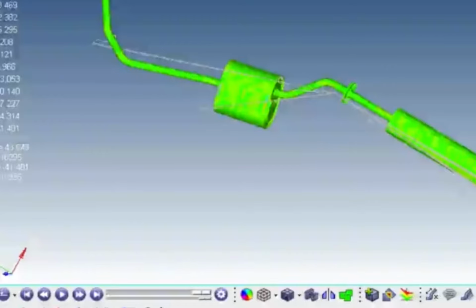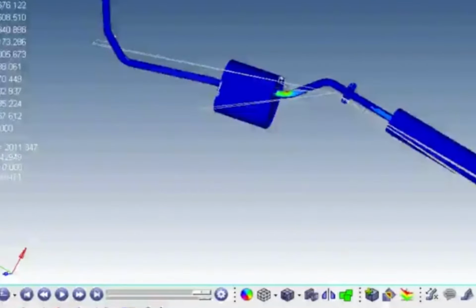So we're reading in the model file. We're reading in the element worst results, and in the results set, we have 20 different quantities. I'll go through and explain what each one is. So we have the various moments of response, starting off with the 0th moment, first moment, second moment, and fourth moment. Now these aren't quantities that you will probably want to use, because they're, if you like, the primary response quantities for the system. But we use those for everything we calculate. So we provide them in case there's something that you want to do special with these results.